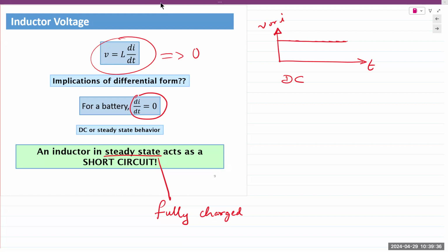Yes. All right. Henry, you mean for the inductor? It's basically, no, that's just an association. So that's a good question. Basically, the question being asked is what is actually Henry? What is the level of one inductance, right? Is that what you're asking? So 1 Henry is the inductance level or the capacity that produces 1 volt for every 1 ampere change in current that's flowing through that inductor. So if 1 amp is being applied to an inductor, and it produces 1 volt across that inductor, then that inductance level is 1 Henry.